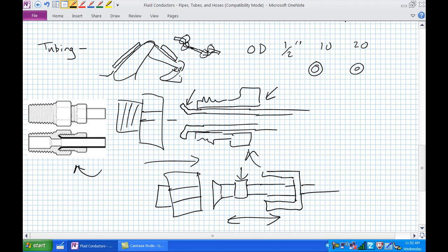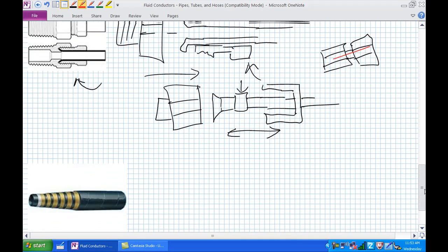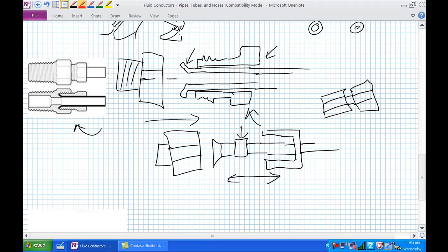There are certain tightening specifications for these. Basically, you're just going to look it up in the manufacturer's fitting tightening specification. The other thing you want to do sometimes is make a witness mark. Here is a connector that you've made. Take a red paint pen or whatever it is, and once you've torqued it down to the proper specification, draw a line across it. When you come back the next day and that witness mark has moved, you know that you need to tighten that again.